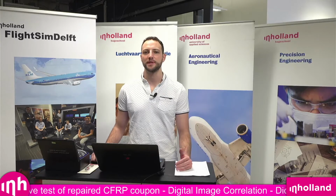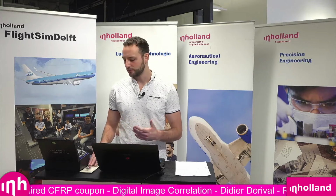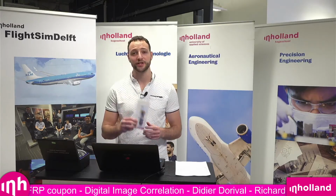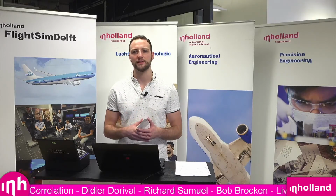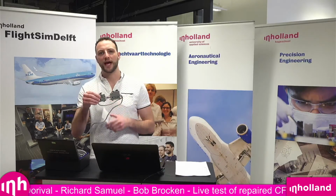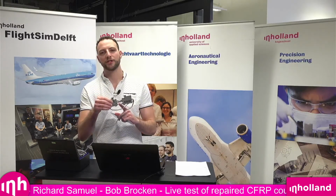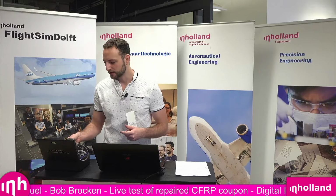Digital image correlation is a contactless type of extensometer. I think a lot of you know that a contact type extensometer is like a strain gauge, where there's a coil inside, and you have to attach it to the sample. When the sample elongates, the resistance in the wires changes, and you can measure the elongation. Or a contact type extensometer, like a clip-on extensometer, where there are two knife edges, one knife edge is locked, and the other can move with the sample as it elongates, also outputting the elongation.